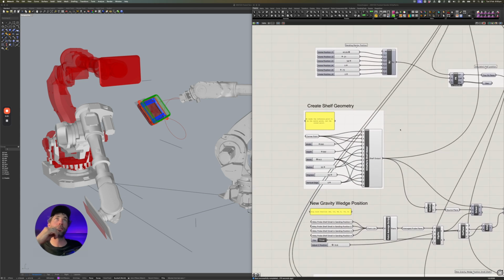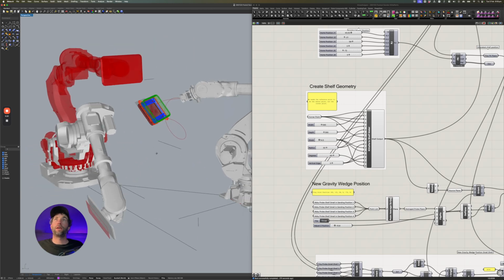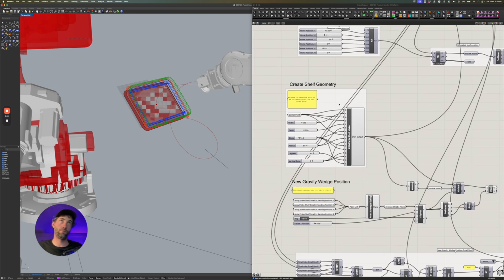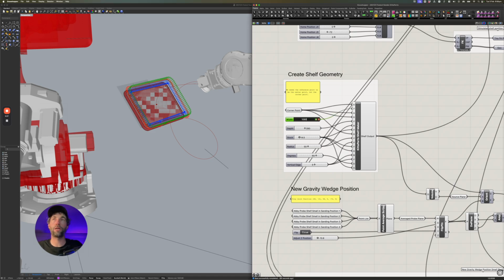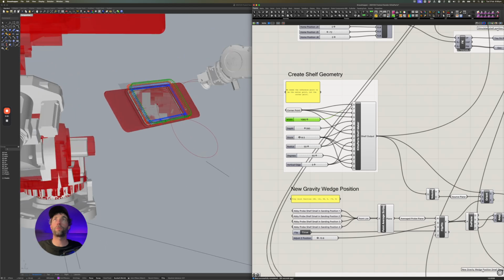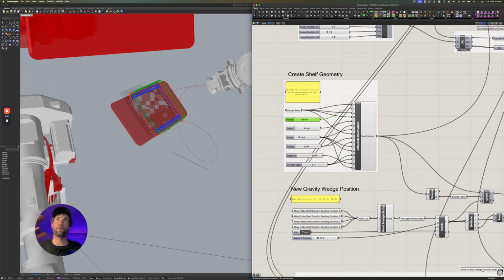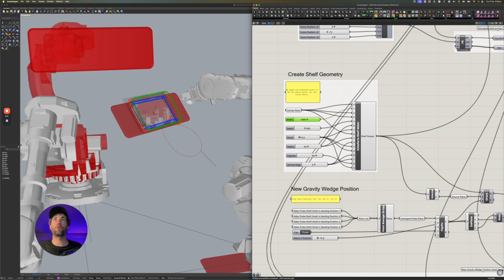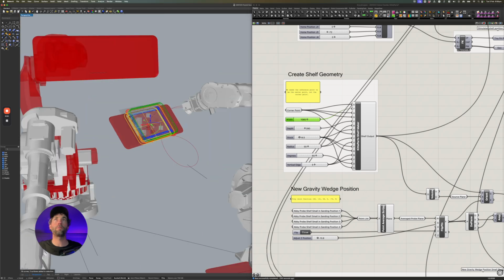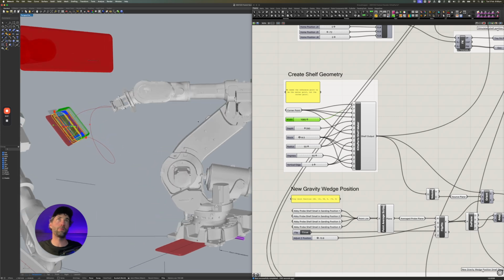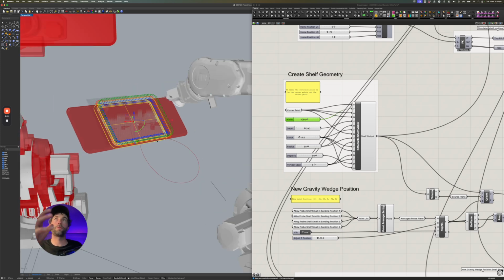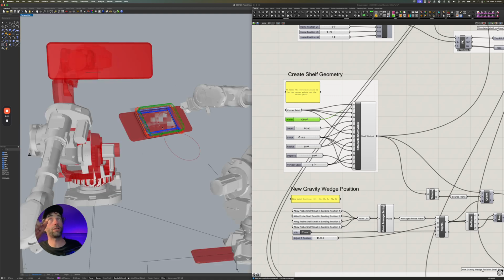No, not really. I'm at a point where small shelves are sanding quite well on the robot, and I'm trying to go to the next size, which is 1080. That's fine, it creates the geometry in the sanding position. That's where Tiny, who's my part handling robot, is going to position the medium shelf to that spot. So I could go ahead and program ABB without too much trouble. Just extrapolate from these toolpaths, get ABB standing in that spot. The problem is I've got to get Tiny to put the shelf in that exact position.